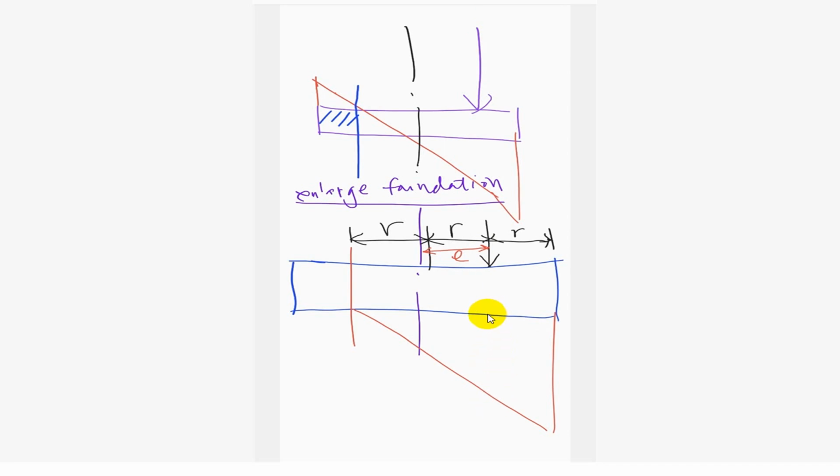The compression block is the soil bearing, which is the compression force acting on the soil. The foundation is adjusted so that the external load from columns or buildings goes through the center of the compression loading block. Do you follow me?